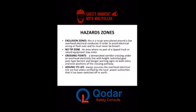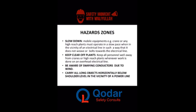Please, as a note of warning, whenever we see an overhead line, and we do not know if it has been in use, please do not go there to touch it. They say you should always assume that lifeline is live because we do not know. So to avoid putting our life at risk, we should always assume that any overhead power line is live and it can give us lots of injury. So we need to be assured that it has been certified by the local authority or it has been switched off for us to start any kind of operation that we need to do.